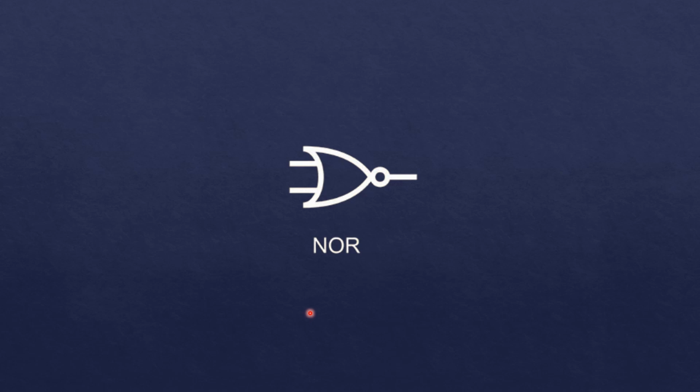If either input of the NOR gate is 1 or 0, what corresponding output are we getting? Let us understand it. In the second input, I'll take it as x. X may be 0 or 1. When one input is 1, the NOR gate adds the inputs, 1 plus x, and negates the whole thing. 1 plus x is 1, as I have shown in the properties video: 1 plus anything is 1.